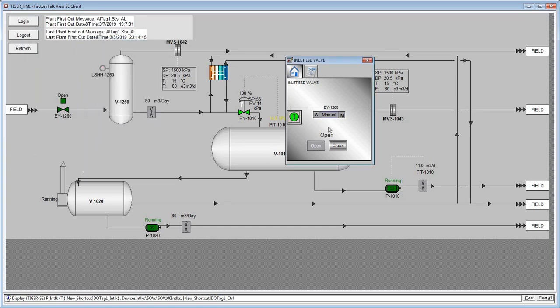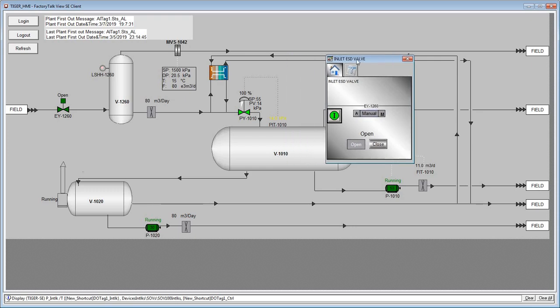And I'll be covering all these objects in a different video in more detail to show you a little bit more about each object and how to use it, but in here we're just basically scratching the surface. So again, here in the settings we can set up things like whether this valve is fail open or fail close, whether it has limit switches for open and close statuses.